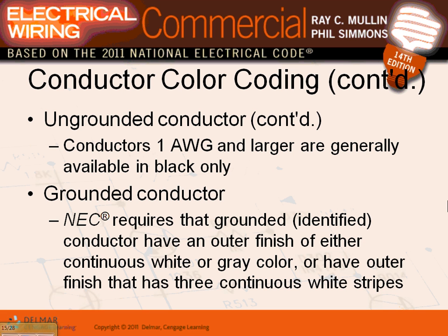Is there any type of device that tells you what phase is what? Yeah, you have phase identification or phase rotation. Phase rotation. Yeah. Here's what the utility does. You start with the utility. When they give you 3 conductors and a neutral, right at the service, they identify phase A, phase B, phase C. That's your reference point. From there, you take it through your building. You have to follow the same configuration: phase A, phase B, phase C.